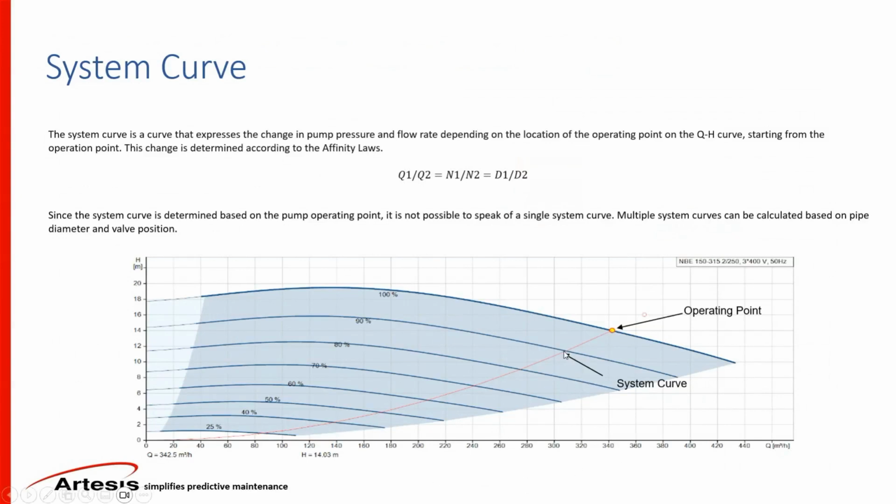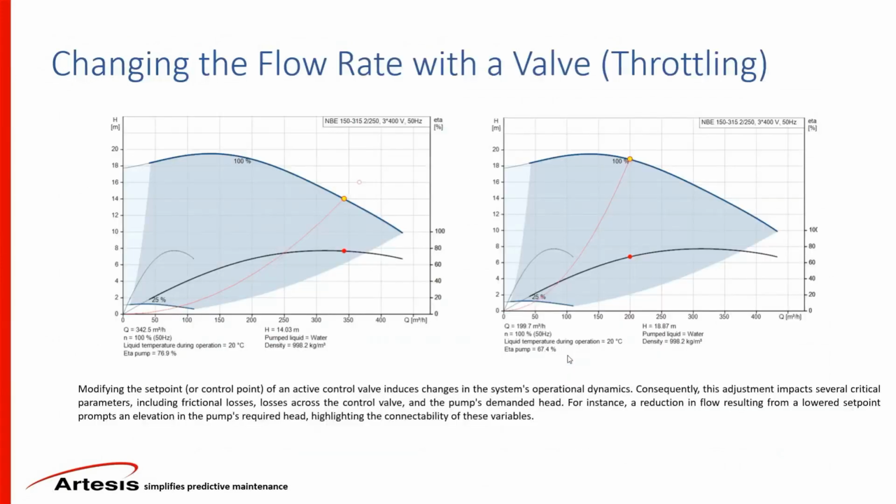So let's say you are at 90%, and your flow reduced by 10% from 340 to 310, and you're calculating this is your best efficiency point. However, if the actual measurement shows that the pump is over here, that would suggest this is not at its maximum peak efficiency, rather it's deviated from that. So of course, this is the information we are after here, and the system curve will be the reference point for that.